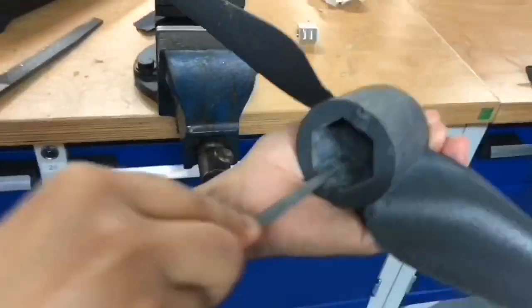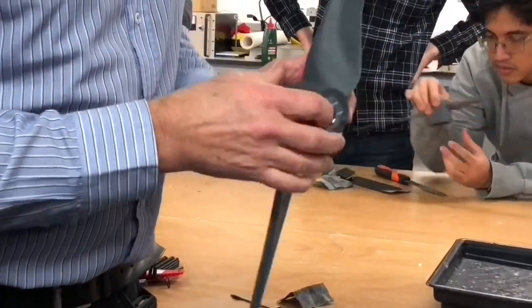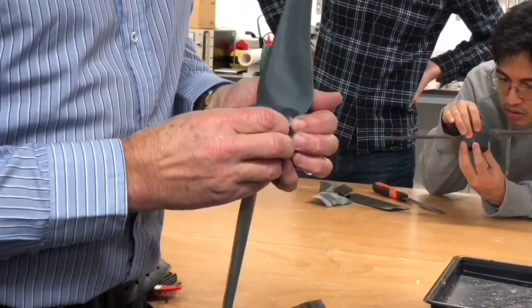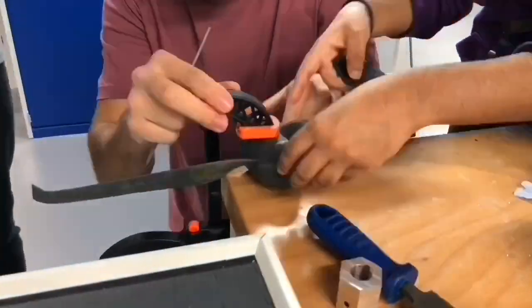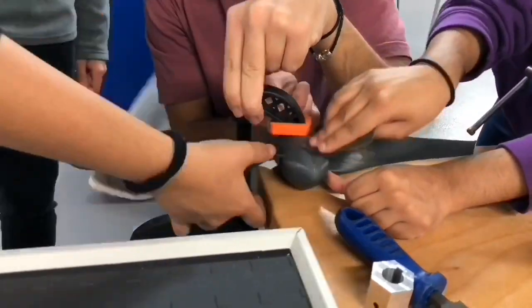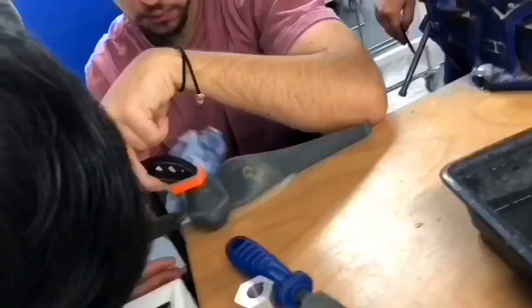The hole for the hub had to be filed down slightly as the fit was initially too tight. Burrs were also removed from the blade and the hole for the hub to ensure a tight fit. During manufacture, care was taken when sanding the nose cone to ensure that grooves in the surface were developed perpendicular to oncoming airflow. This triggers pockets of turbulence, delaying flow separation from the nose cone surface.